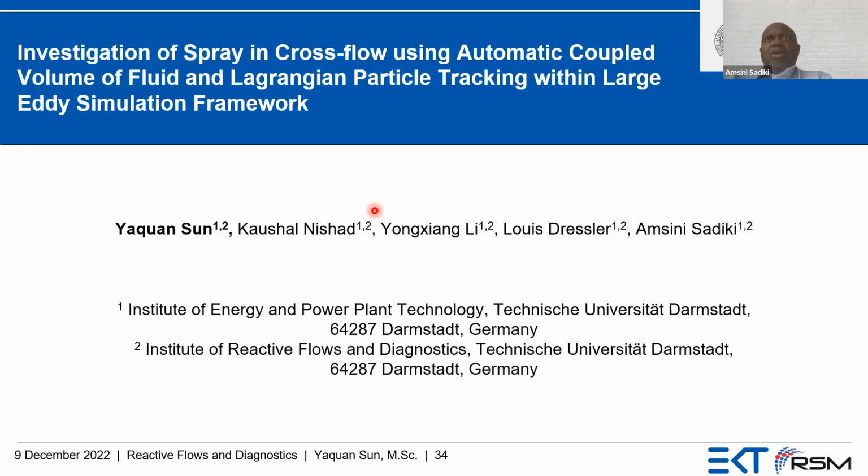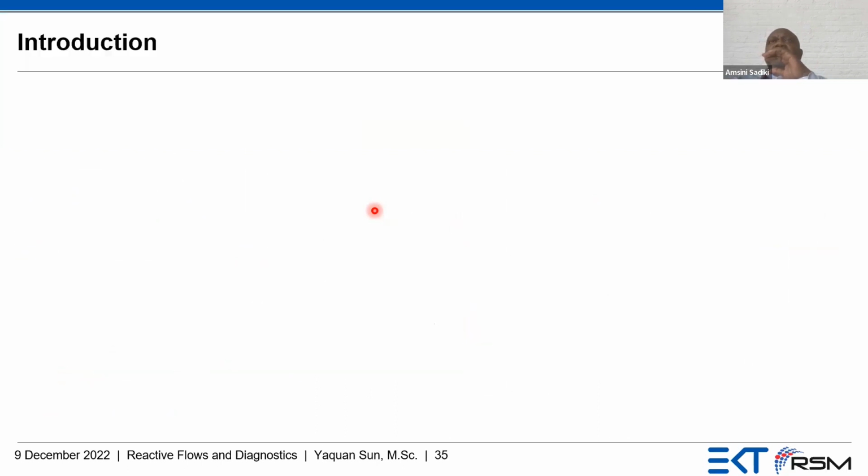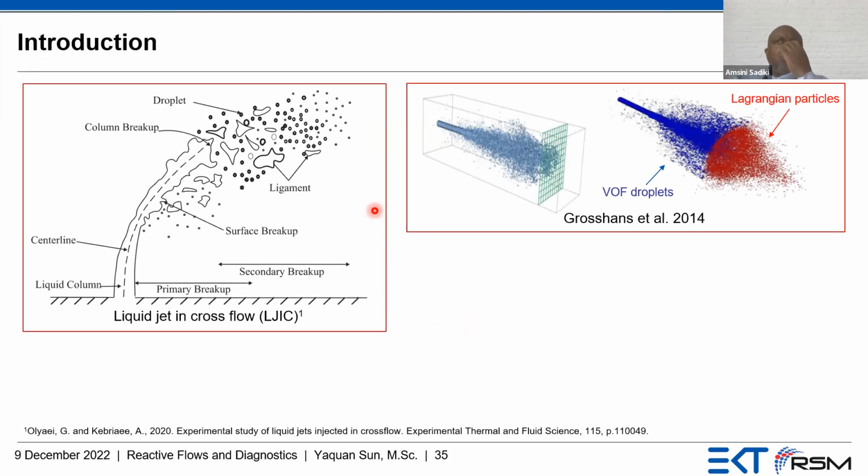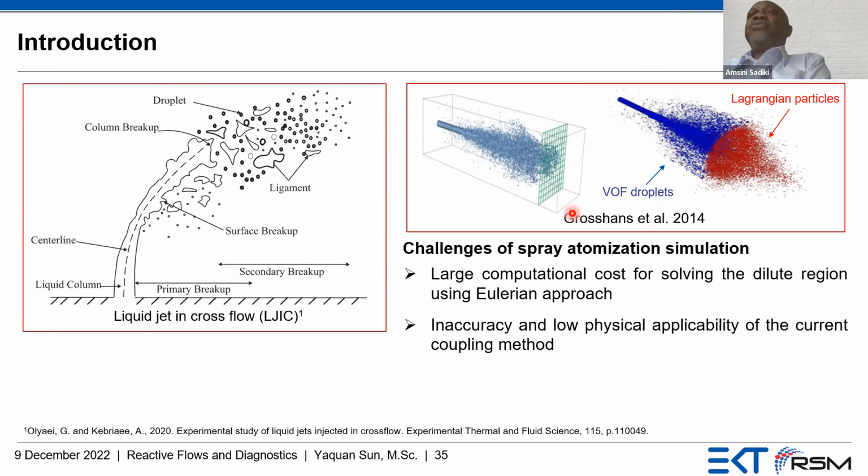Let me now show you how we try to couple this volume of fluid to Lagrangian. There are these two options. There is the option to do VOF first and to generate droplets here, as we did before, and to get this distribution as inflow condition for Lagrangian particles. This was the work from Gauss-Franz. This was also some work done by Hermann, but Hermann was the first to try to make a seamless coupling, but he didn't use VOF, he used level set and Lagrangian tracking.